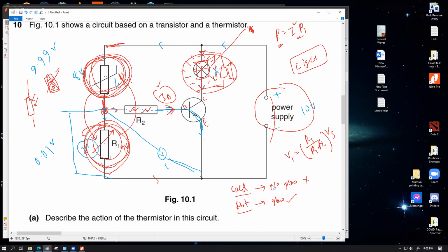If R2 was not there, what is possible is that whenever the voltage through this branch would be pretty significantly high, if R2 did not exist, this is a perfectly straight line, IB can become significantly large as well, which means in this case, IB would drain, because this pathway would be open. Your bulb is gonna glow and it's gonna pull its own current. Let's say currently it is pulling 2 ampere, and let's say the way this transistor is designed, to make sure that the bulb operates at 2 ampere, you need to have, let's say, 0.02 ampere as IB.